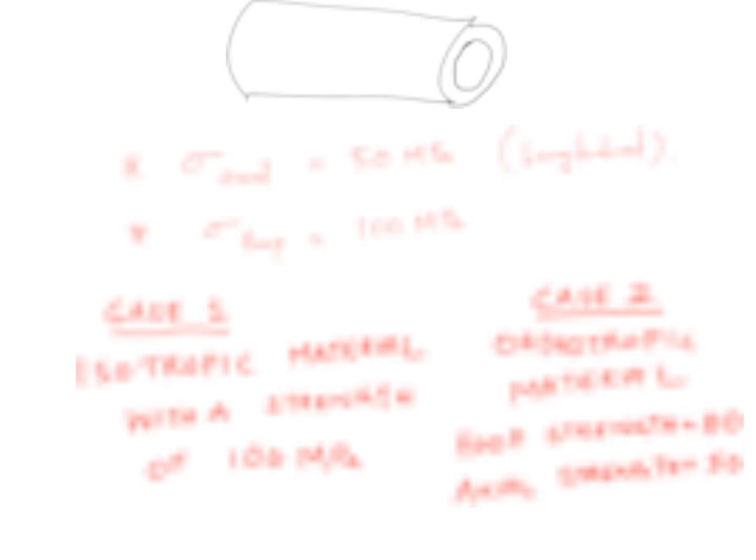we have to select materials for a particular structure after looking at the kind of stresses that the structure will see. If the structure is in a configuration where it will experience a higher stress in one direction, the structure has to be strengthened in that particular direction.